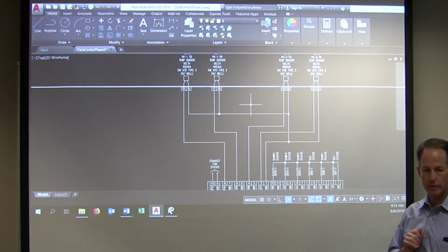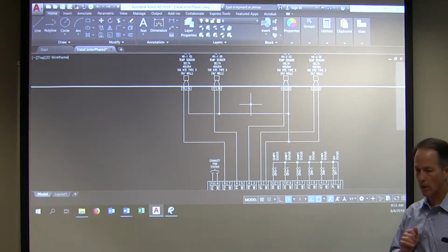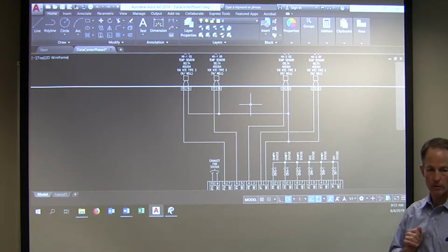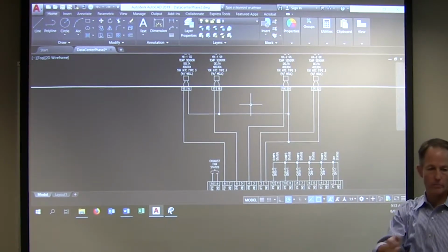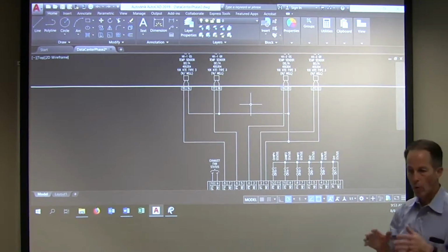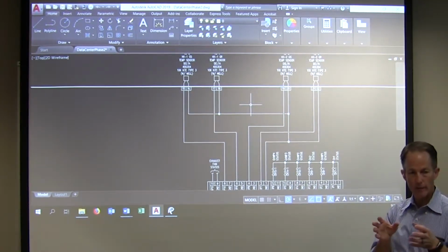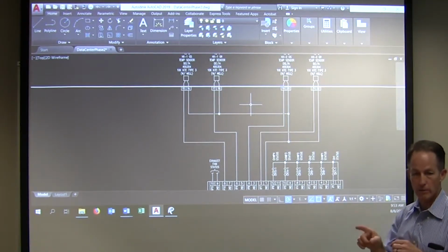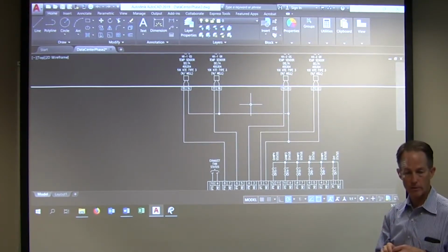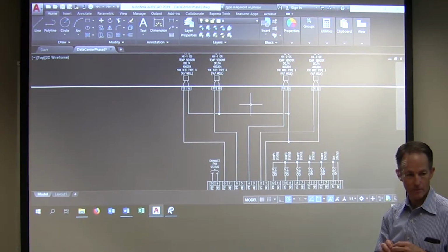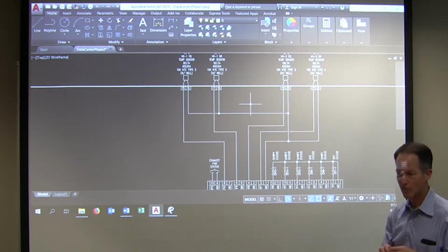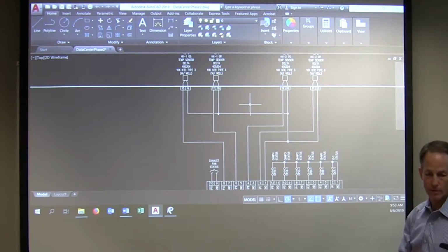So we're 21 something, right? 21.24. And you just get your temperature for the pipe off of your thermometer, or maybe you have one of those thermal guns that you can shoot it with. So right there, you have verified that the sensor is working. True or false? False. Just that the thermistor is working, if you've got that temperature.